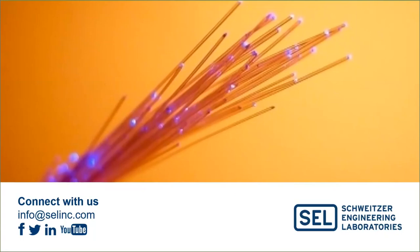Yeah, it's going to be the exact same scenario. There is going to be a little bit of attenuation due to the difference in the size of the cores. Obviously, it's more ideal to make sure that your fiber optic cores match, but it's not necessarily the end of the world. There might be some attenuation there, just from the difference in core size.